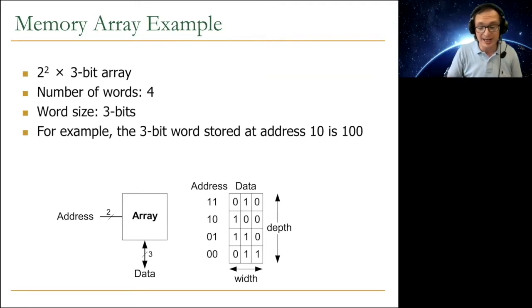Why is the array organized this way? So that you can pack together many cells at the same time, right? If you have an array that's like 16,000 rows and only 64 bits, let's say, in each row, your density is lower, basically. People have found out that more or less rectangular arrays give you good density.